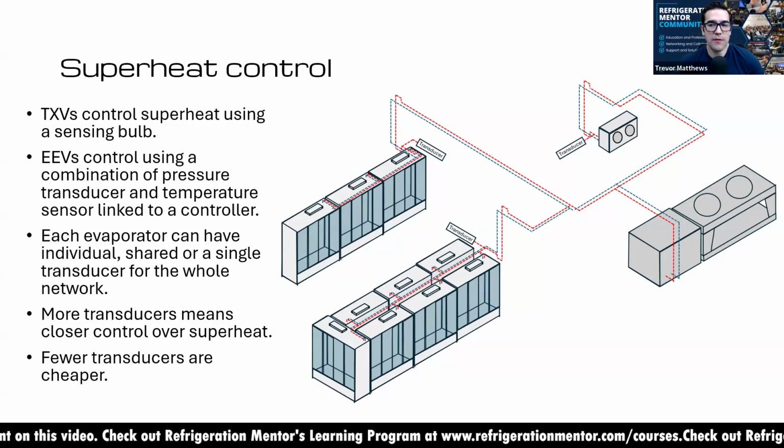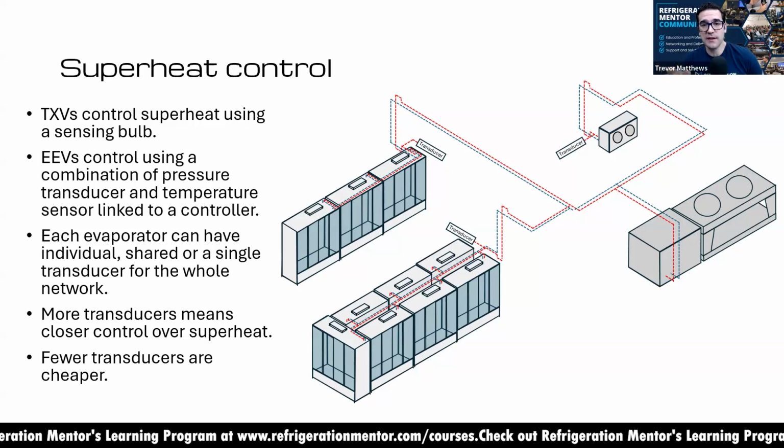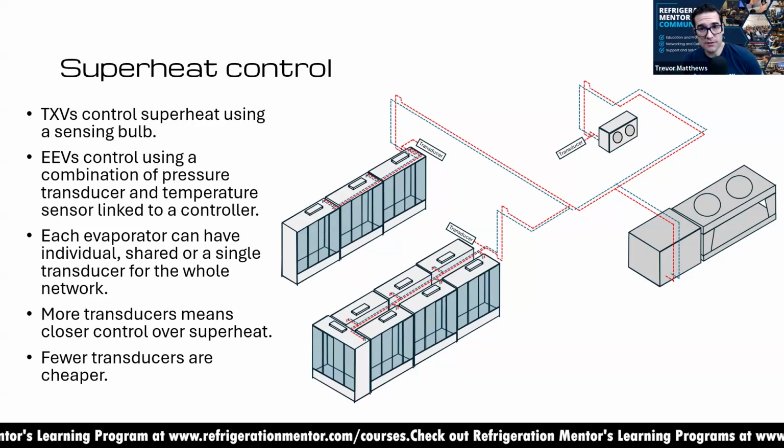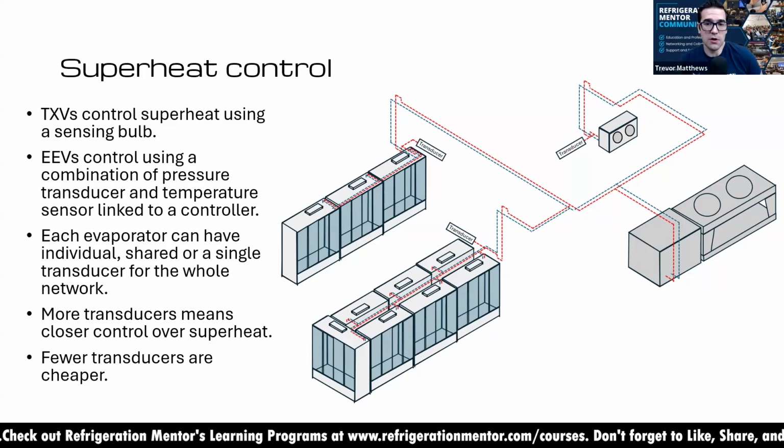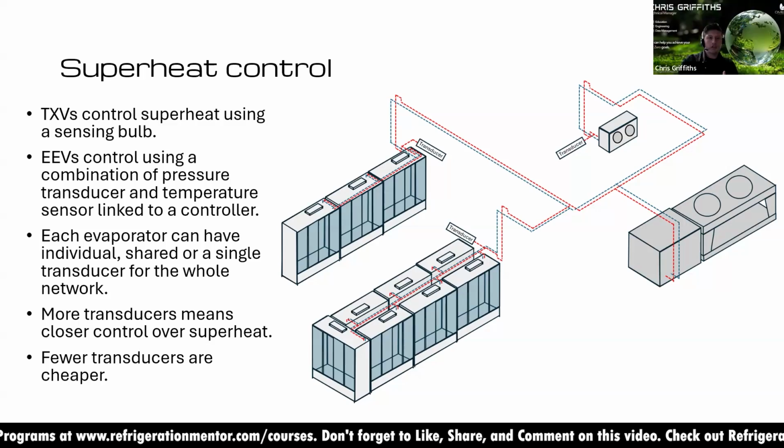For me, I've always had every coil have a transducer, because now I know what that specific valve is doing, like the EEV, as well as that coil. Now with a transducer getting, for example, those 7 cases, as long as it's piped properly and you don't run into any issues, those valves will work great, but what happens if you have one transducer but you have 2 frozen up coils? How does that affect all the other cases now with one transducer? They're shared across it, I would say.